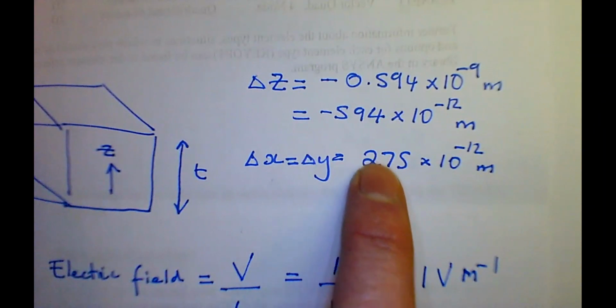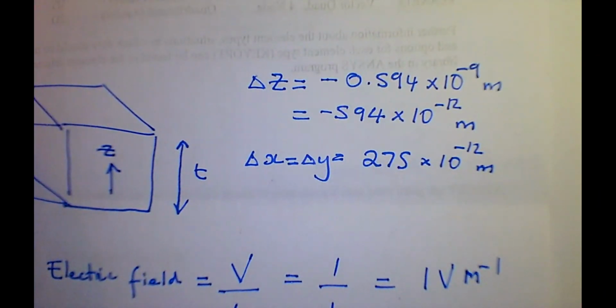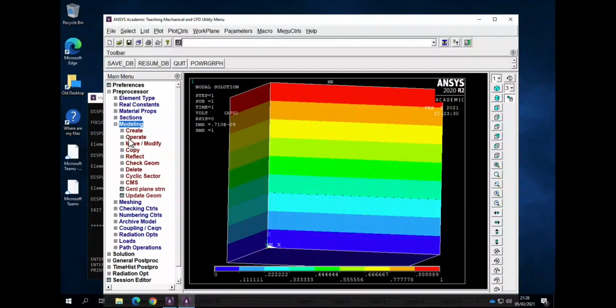You might be saying, well, hang on a minute, I didn't enter D33 into the model. But in fact, we did because we input the charge coefficients as the material properties, and that really is linked to the strain properties as well.